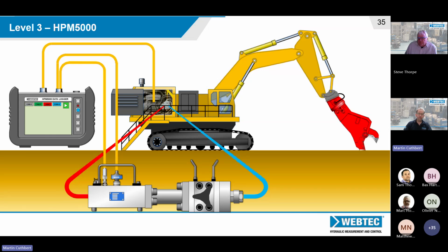And actually that seems to be a common theme when we talk to customers. It's often where they're not quite sure where the problem is inside a more complex hydraulic circuit, particularly where flow is being supplied to another function. If something's not working, there can be a bit of finger pointing. Go in there and test each device independently, and you can work out where the problem really is.